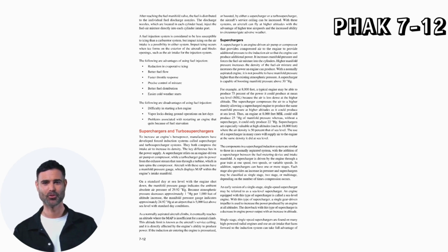Superchargers. A supercharger is an engine-driven air pump or compressor that provides compressed air to the engine to provide additional pressure to the induction air so that the engine can produce additional power. It increases manifold pressure and forces the fuel-air mixture into the cylinders. Higher manifold pressure increases the density of the fuel-air mixture and increases the power an engine can produce. With a normally aspirated engine, it is not possible to have manifold pressure higher than the existing atmospheric pressure. A supercharger is capable of boosting manifold pressure above 30 inches mercury.